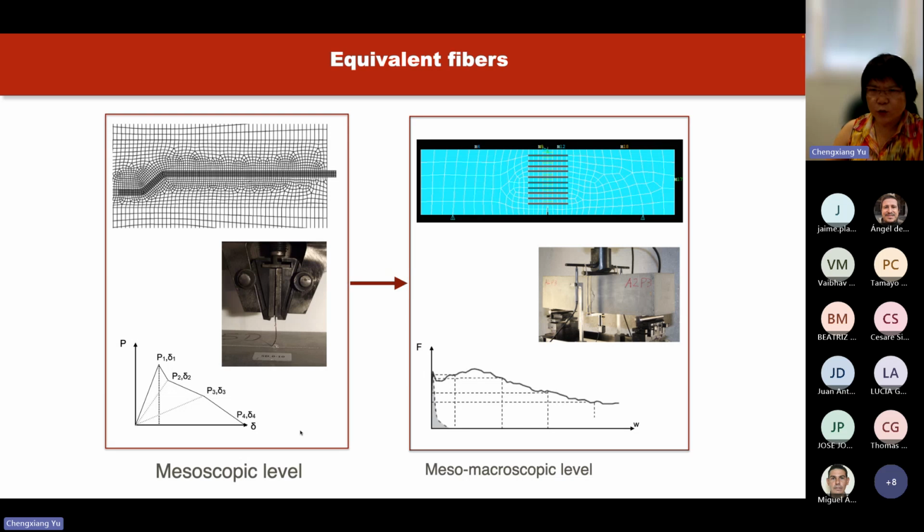On the mesh, the first toy models that we have done have all the fibers parallelly distributed, but each fiber carries an individual constitutive law depending on its real inclination angle.